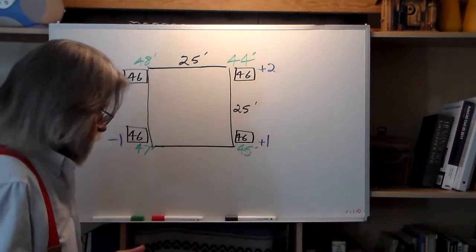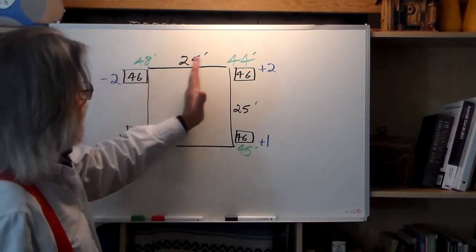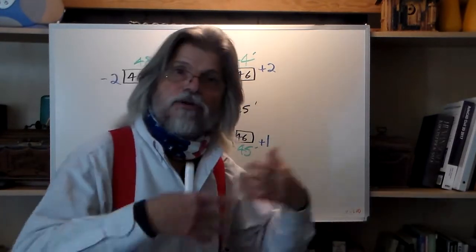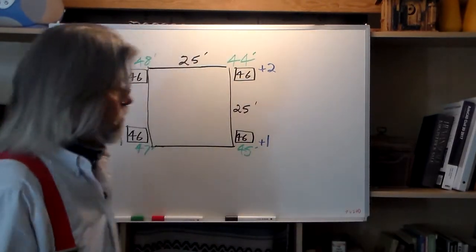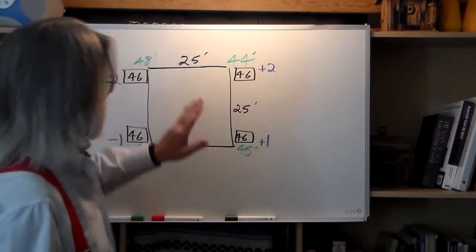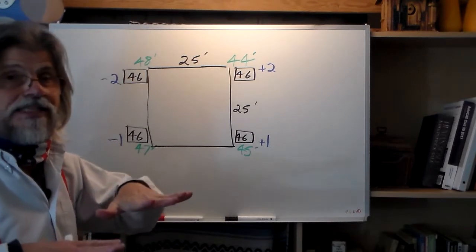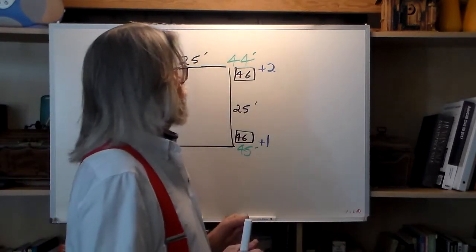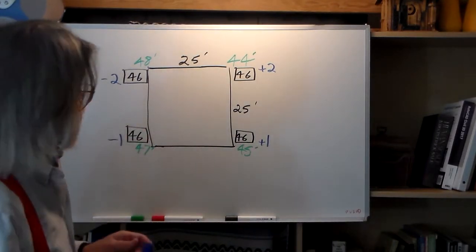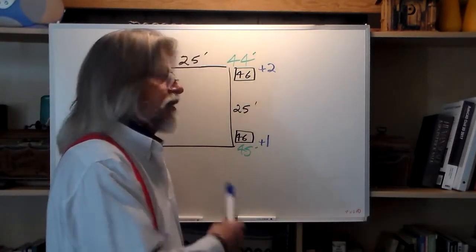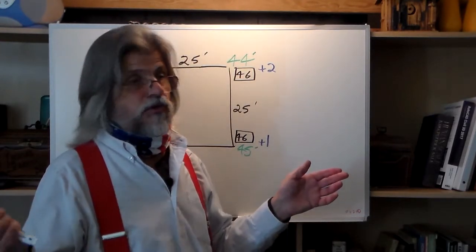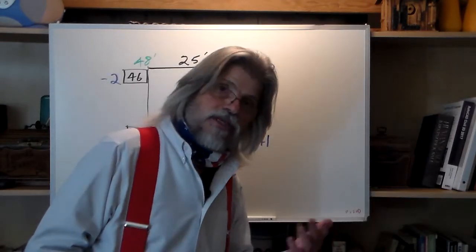That means that a certain area of this will be what's called fill. It's where you're filling dirt in, you're piling the dirt in there, soil, if you prefer. And here we're going to be removing the soil to bring the area down to the design elevation of 46 feet, because it looks like that's the number I chose. Once again, I'd like to remind you that all of these examples that I work up here on the board are all made up on the fly, so we're going to make mistakes sometimes, and that's how we learn.